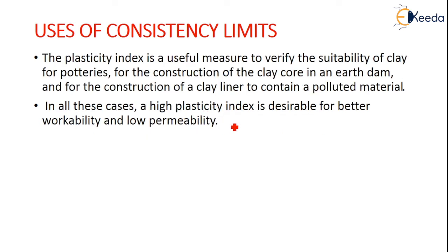Coming to the plasticity index, it is very useful to verify the suitability of the clay for pottery, for the construction of a clay core in an earthen dam, and for the construction of a clay liner to contain polluted material. So in all these cases, a high plasticity index is desirable for better workability and low permeability.